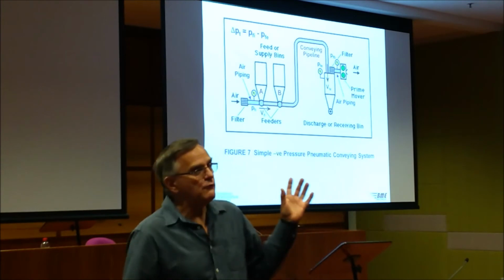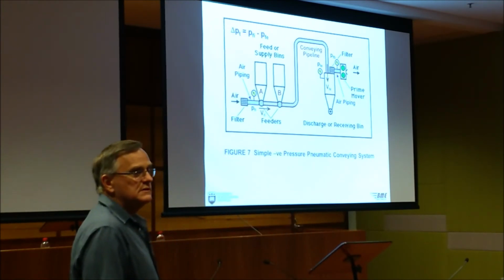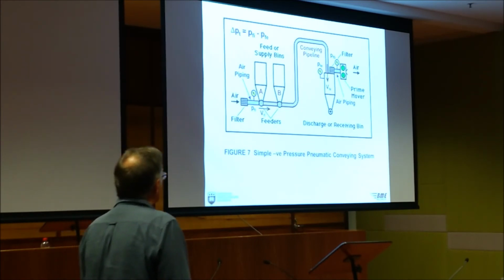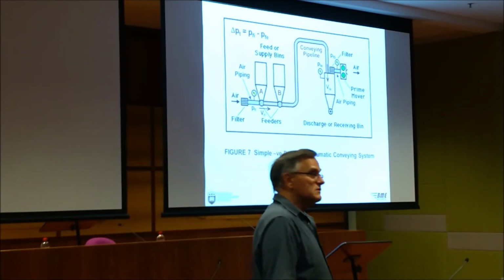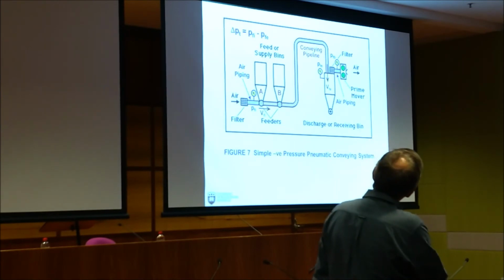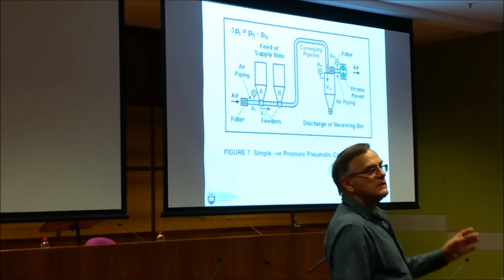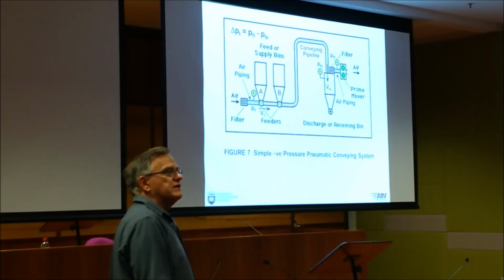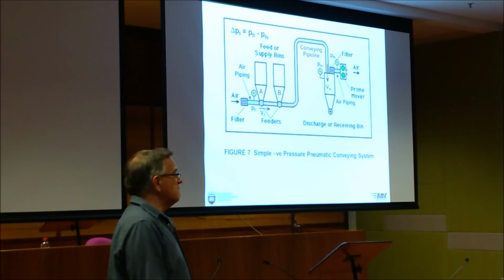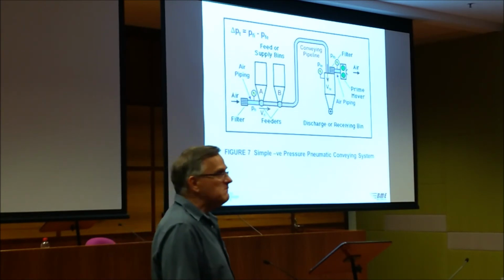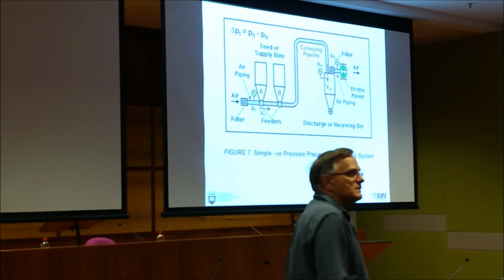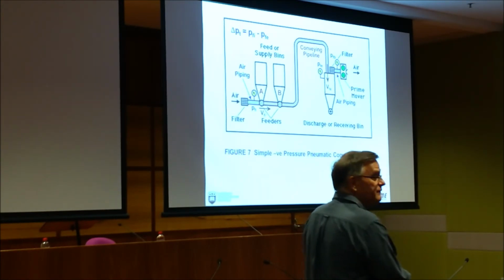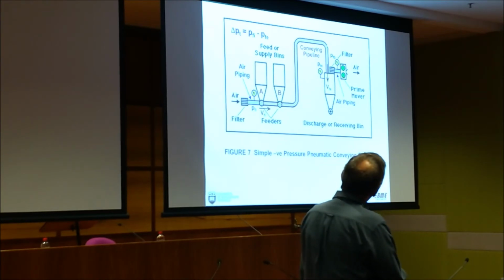And later, I'll talk about wear and velocity. It's horrible what happens at those numbers. And I said, look, I can give you a simple solution. We just stepped the pipeline at the end. We increased the diameter of the pipe, and we dropped the velocity down. We got it down to about 40 metres per second, something like that. Yeah, wear problem disappeared. Yeah, the last bend is always the one that wears out first. That one will wear out first.